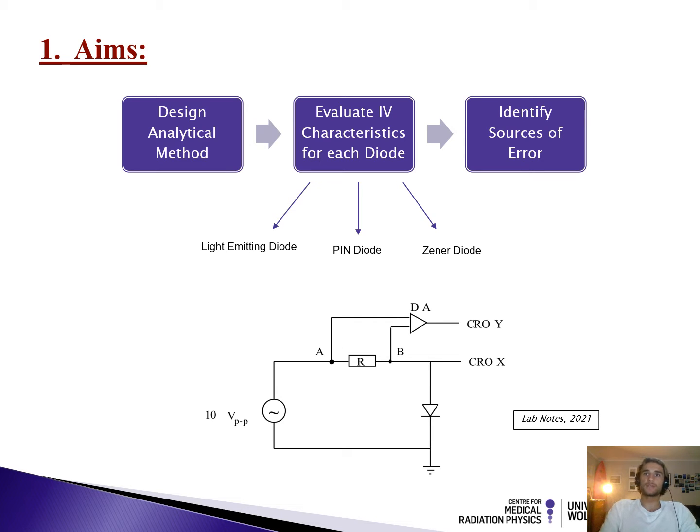The characteristics for each diode were monitored continuously on a cathode ray oscilloscope by setting up a circuit using a function generator to generate a time-dependent voltage. To accurately measure the voltage drop across the 100 ohm resistor, a differential amplifier was used to minimize current leakage.